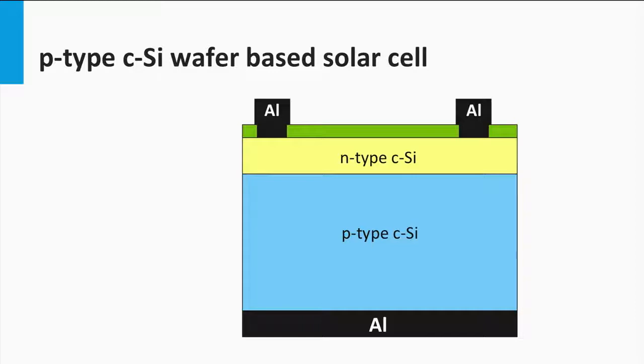As a consequence, it is preferred to reduce the area of the interface between the metal and the semiconductor to minimize the recombination at the interface defects as much as possible, and to have the emitter directly under the contact as heavily doped as possible. This higher doped region is indicated by N++.